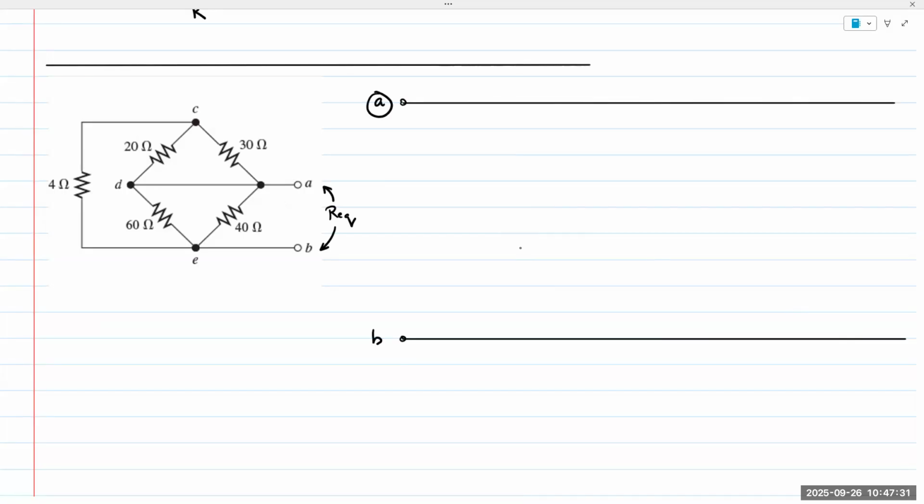I'm going to call them A and B. The objective is to draw every resistor vertically, starting from A and making our way towards terminal B. At the end, all resistors are in parallel branches, and we can simply combine them either in series or parallel to find Req. This technique does work on most circuits. There are some circuits that are not reducible just because of the way the connections are. For those circuits, we can't find Req by any normal means.